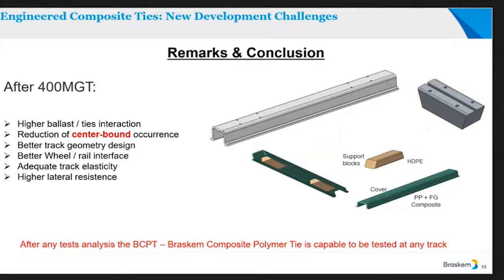So as I told you, after 400 MGTs, the high ballast tie interaction is much better when you compare with timber and concrete ties. We measured the reduction of center bound occurrence. We get some better geometry design on the track. One proof of it: we reduced grinding passes by 3 times, because the gauge stayed in the same situation. So we believe that we can make better grinding performance, because the rail stays in the same position.